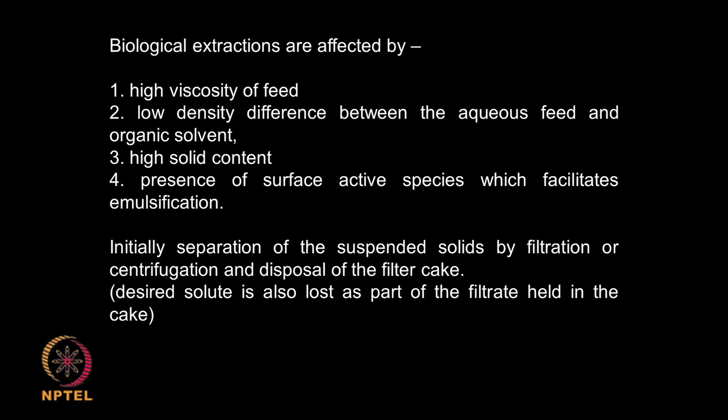It could be a metabolite, it could be a protein or enzyme and so on, but there are many issues here in biological systems because the feed will be highly viscous. The feed that is coming out of a fermenter broth is going to be very highly viscous, and then there could be low difference in the density between the aqueous feed, that means the fermentation broth, and the solvent which you are using. That is another problem.